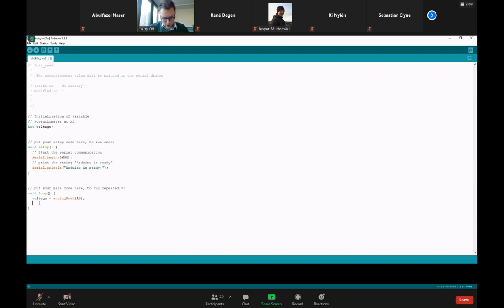And now we want to print this value to the serial communication interface. Therefore, we use the function Serial.println as well. We did it before. So Serial.println, open the round brackets, and write down our variable voltage.